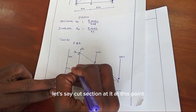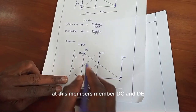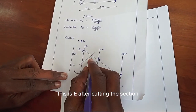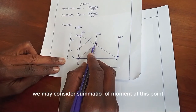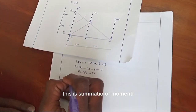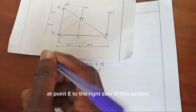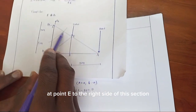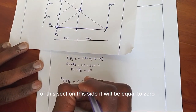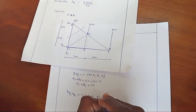Let's say we cut the section at these members: member CD and AE. This is E. After cutting the section, we may consider the summation of moment at this point. This is the summation of moment at point E, to the right side of this section, this side. It will be equal to 0. Clockwise direction positive, anti-clockwise direction negative.